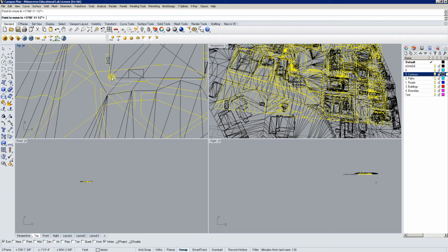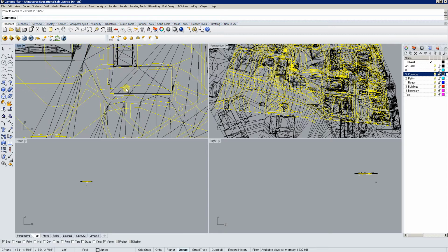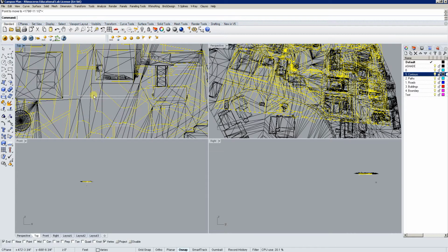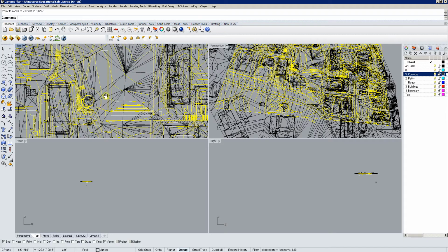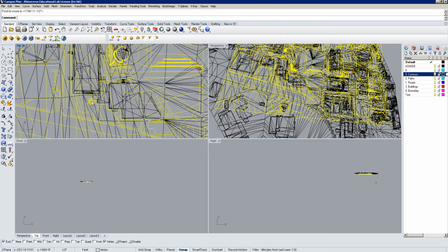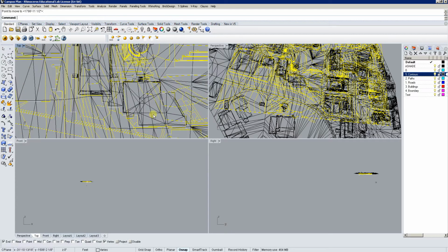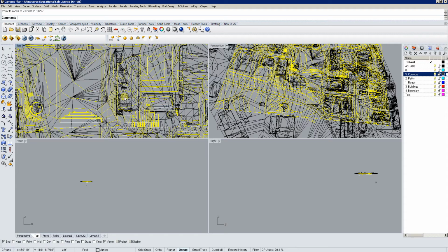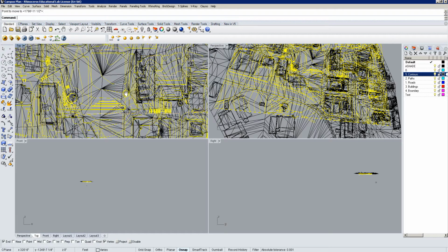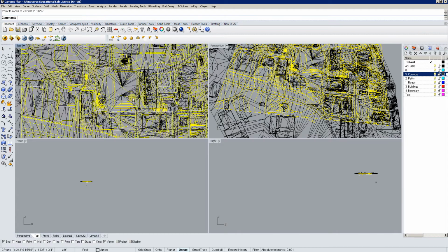And you can see there's a, well, we call it low poly. We reduce the level of detail. There's also, the CAD files are sort of a gathering of 10, 15 years of CAD files done by different people, so not everything fits. Our 3D models were generated from LiDAR, which you guys have seen in the past. It's a laser scan. So all the little 1 or 2 foot distances there can be either a bad drawing or a bad interpretation of the LiDAR. It depends. So you just gotta kind of realize there's a fault tolerance on all these models.